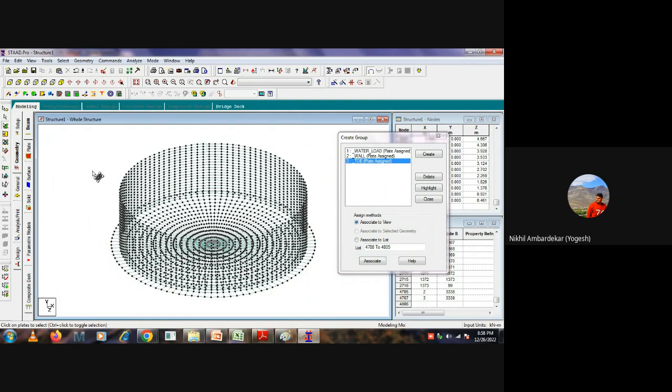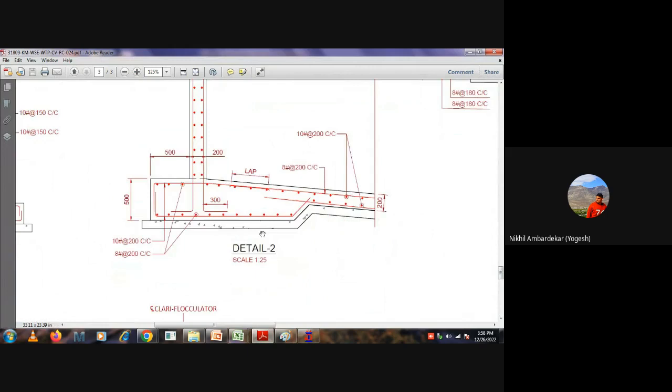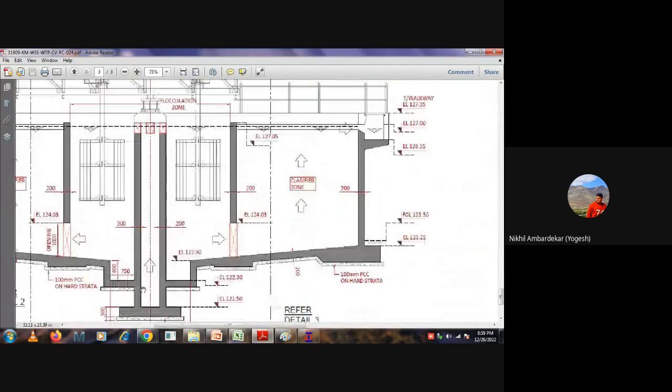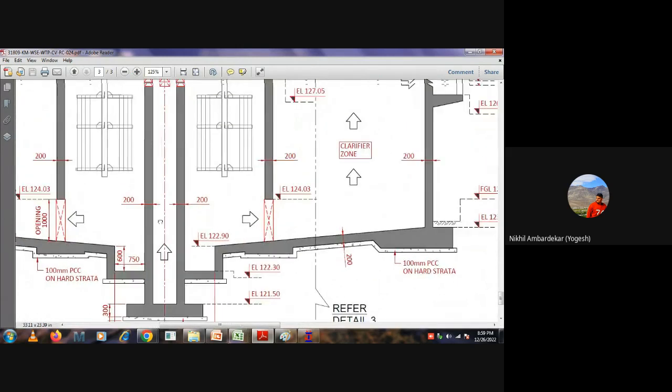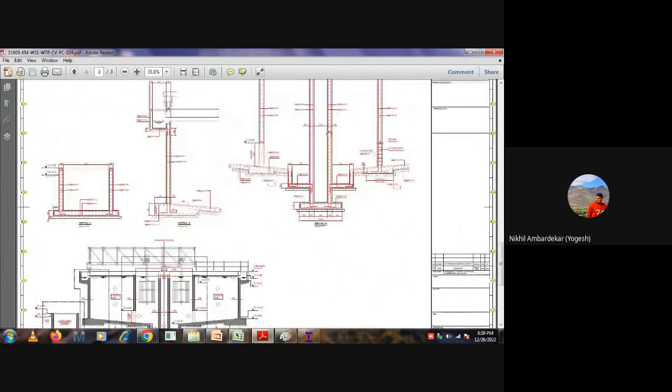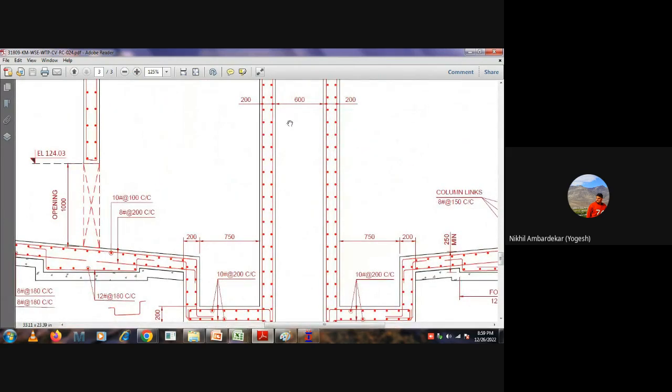Now we want to add the central wall, which is going to support the bridge. So what is the diameter of that central pillar? The 200 mm wall thickness, and yes, 600. So 800. So we need to add a central pillar of diameter 800.